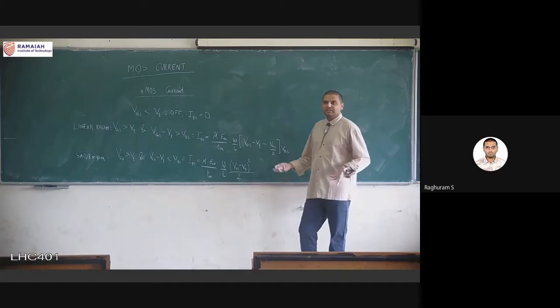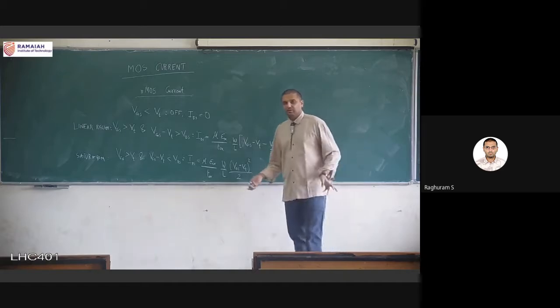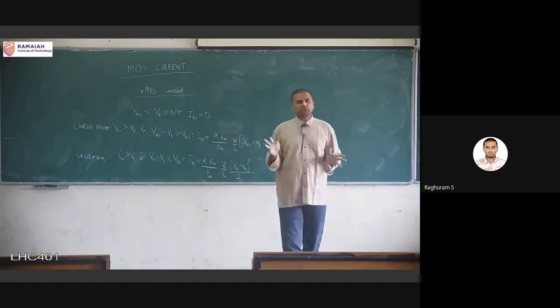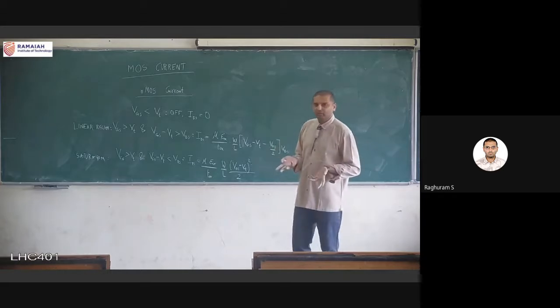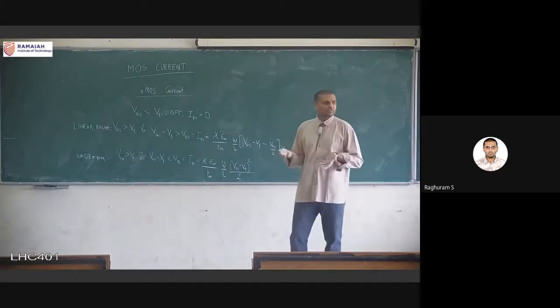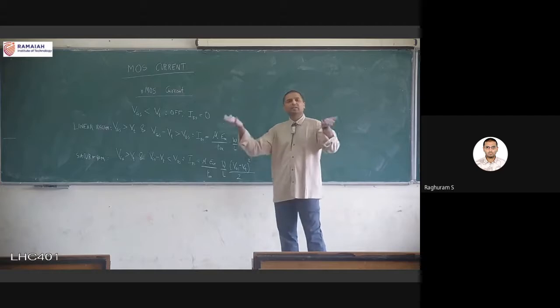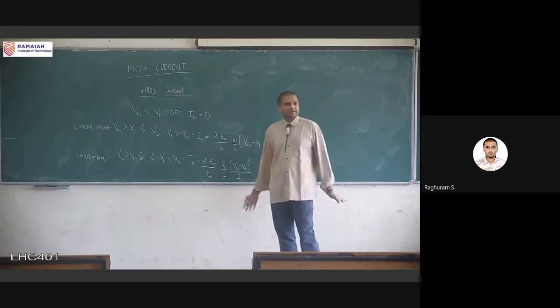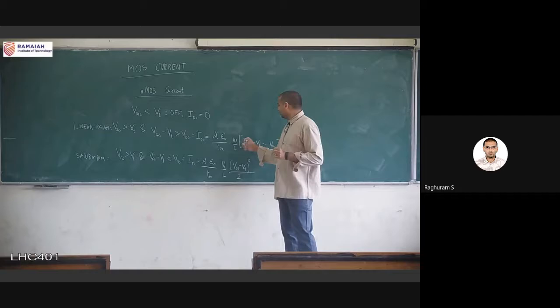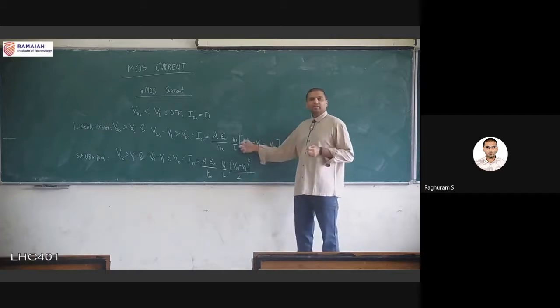The VGS and VDS, even though we have different names for them, both of them are at power supply voltage or at 0. These are the only two values. And power supply voltage for 65 nanometer, everybody knows it's exactly 1.2 volts. Nobody changes that at all. So that 1.2, these two numbers also cannot be changed.